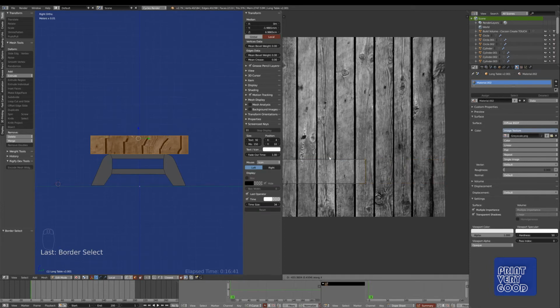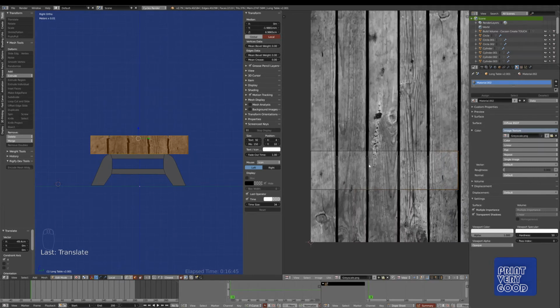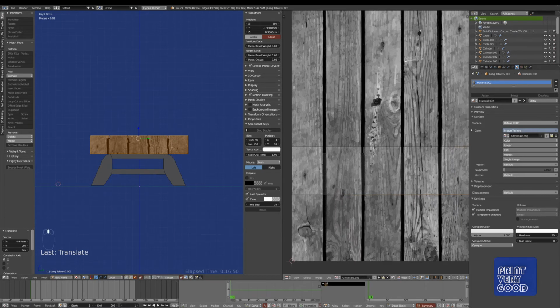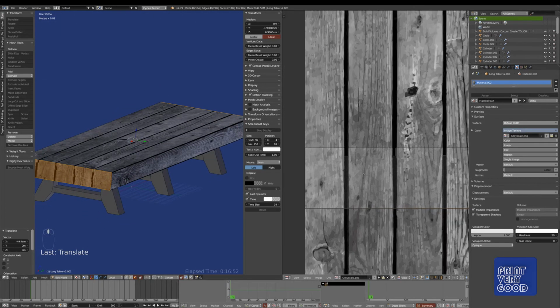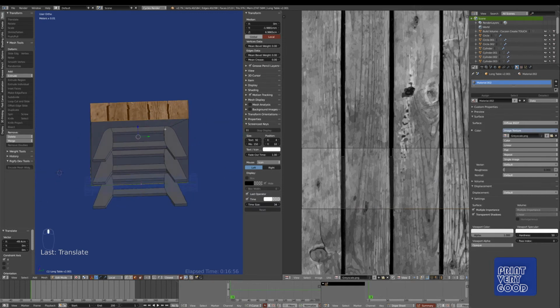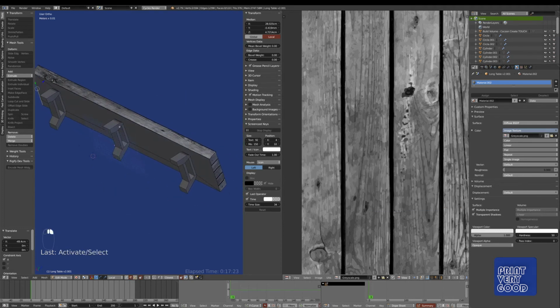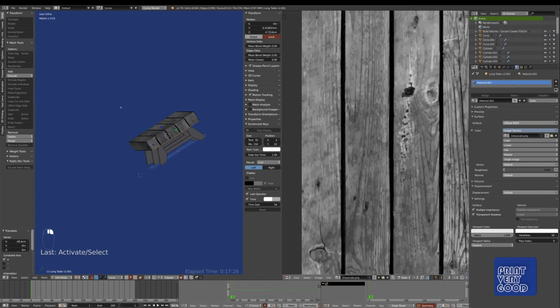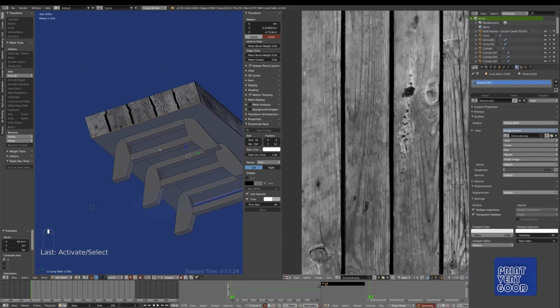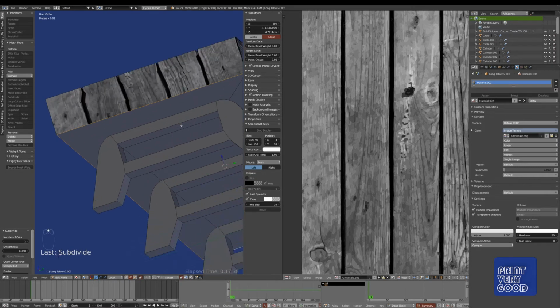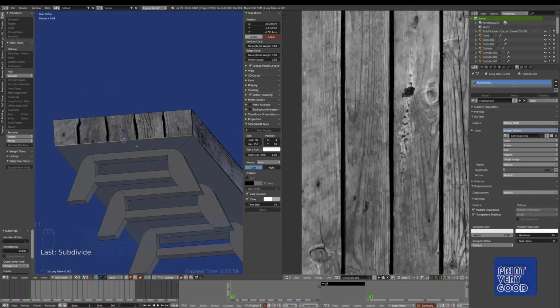Now, as you can see here, we do have a bit of an issue, a bit of tearing happening there, and that's because I don't have geometry coming down from those top notches down to the base of the polygon or to the edge. So I'm going to need to build in some geometry there to fix that. I'm just going to switch to edge mode and add some vertices into that edge by pressing W, subdivide, which will give me vertices I can then join together to form polygons on that face. Just subdividing it a few times to give me plenty of vertices to work with.